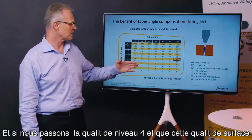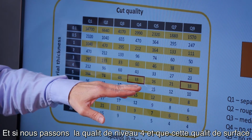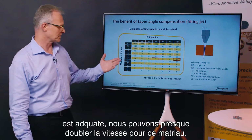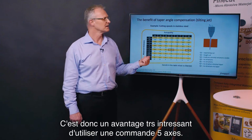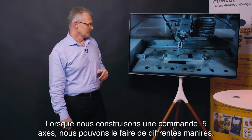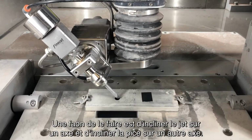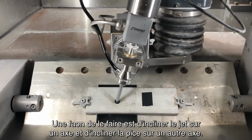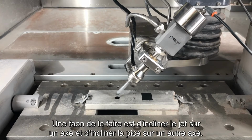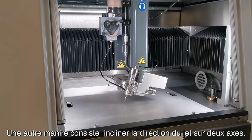And if we move to quality number 4 and have an adequate surface quality there, we can almost double the speed for this material. So this is a very interesting benefit of using the 5-axis control. When we build 5-axis control, we can do that in different manners. One way to do it is to tilt the jet with one axis and to tilt the part with another axis. Another way is to bring 2 axes on the jet and to tilt it in 2 directions.